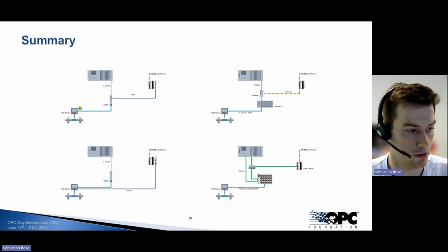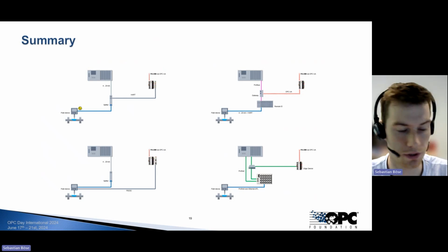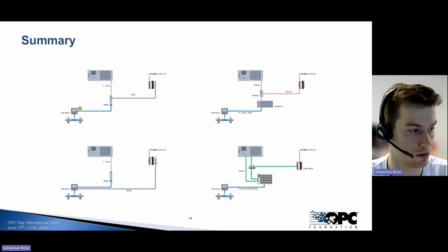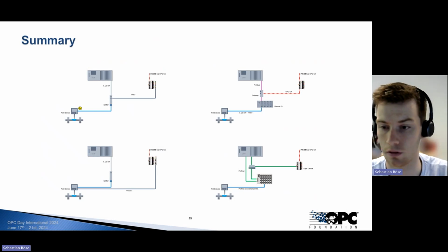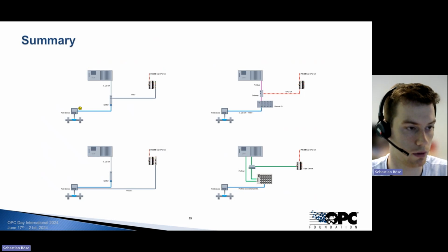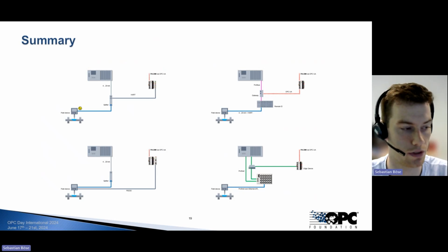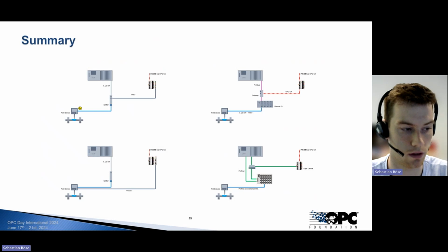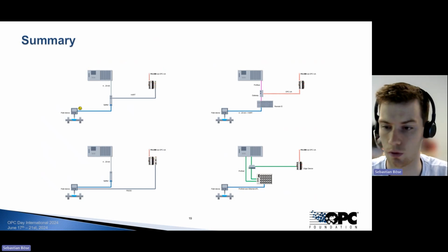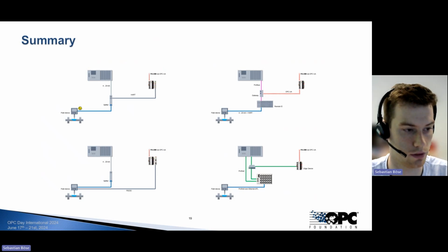So in short summary, we've done a couple of these implementations in the past. They worked pretty well, but of course there are really, really many out there which we need to implement in the future. For example, do this whole Profibus setup, finish that. We also want to use Modbus TCP in the future, or maybe directly connect through OPC UA or Profinet through Ethernet APL to Ethernet APL field devices, which is also an option in the future. So this is something we need to do, but we are in a good way right now to finish all this, or to build up this whole NAMUR Open Architecture for all the existing field devices down there.